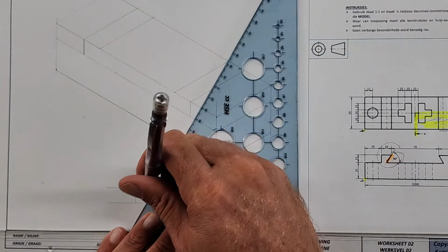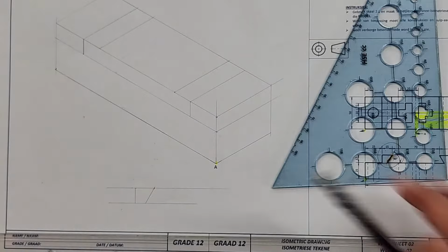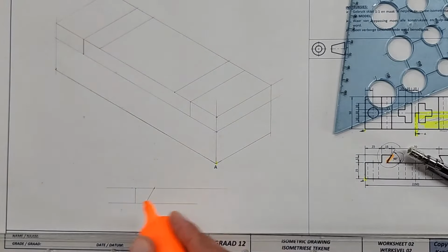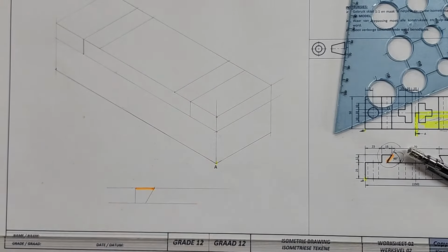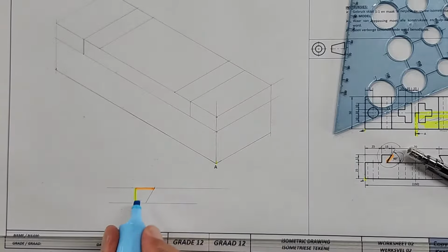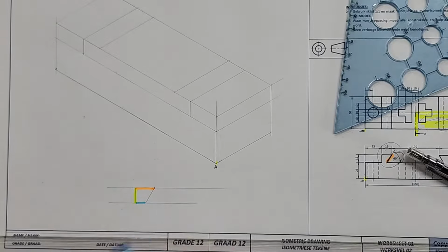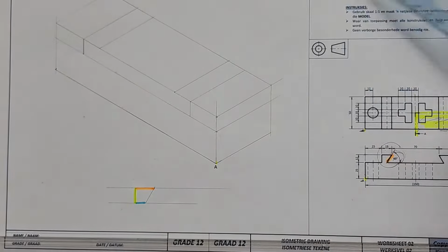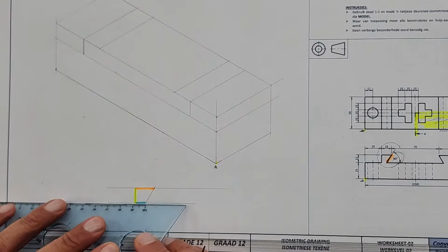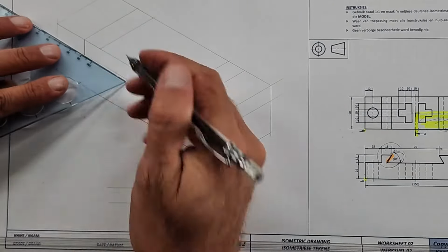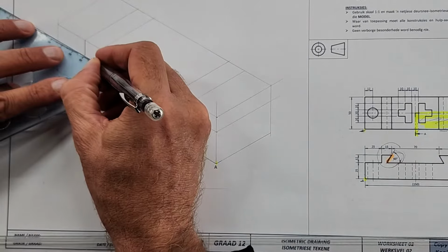What we've done now is, this was known to us. This was the 15, yes? This was the 12, yes? This was 60 degrees, and what we've determined is in fact this distance. That blue. Now I'm going to take my ruler or your compass, whatever you use to measure, and I measure that, and mine is on 8, so I come down here and I do my 8.